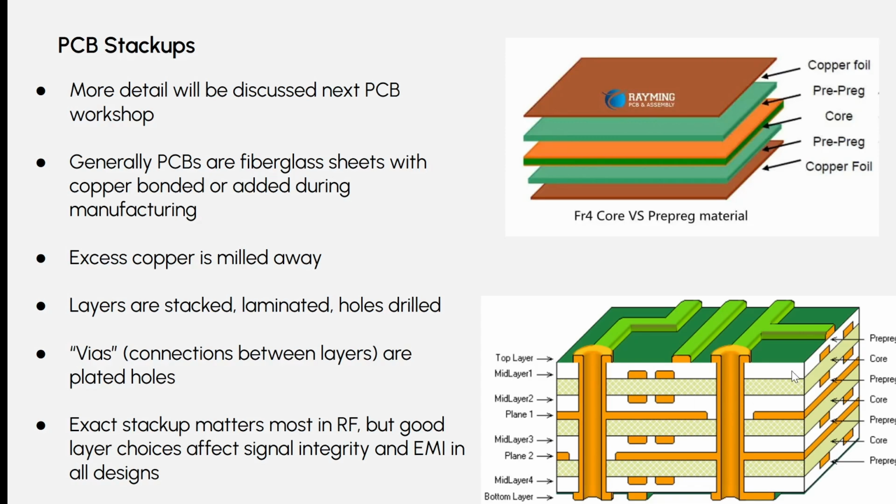This is the main thing you need to know. In terms of doing a digital layout, some small test project, you probably don't need to worry about the physical spacing of these layers, like how thick is the core, how thick is the copper. Those aren't things you really need to worry about, although you definitely should know the layer count and which ones are closer to each other.